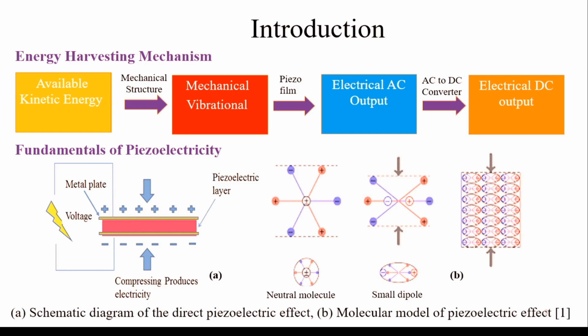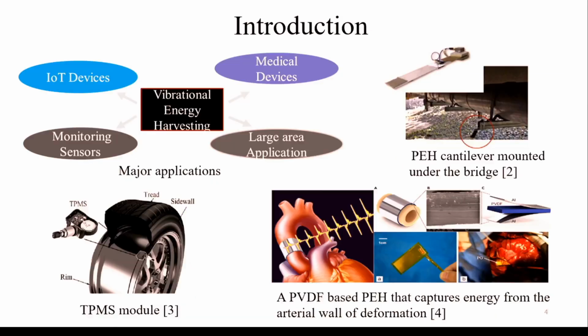In the bottom half, I have mentioned the principle of piezoelectricity. For those who are aware, you can see a cantilever with piezoelectric material sandwiched between two electrodes, bottom and top, and when any stress is applied on it, it generates a charge across the cantilever. This is basically the principle behind this energy harvesting technology.